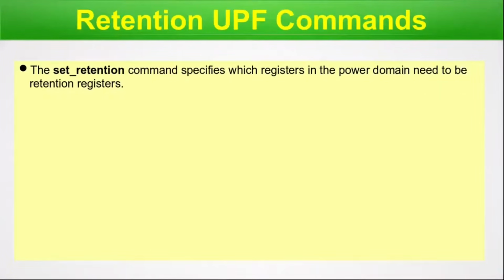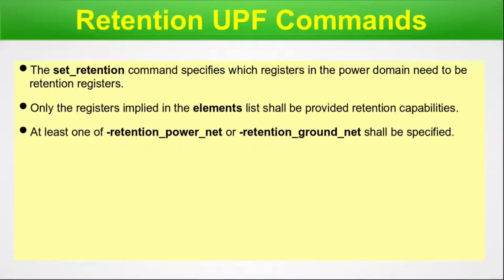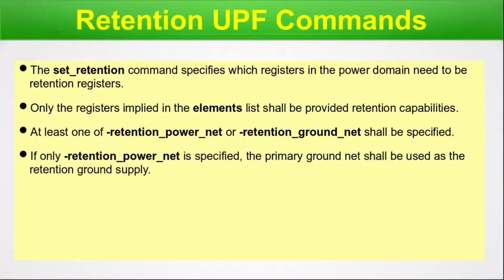The retention UPF commands. The set_retention command specifies which registers in the power domain need to be retention registers. Only the registers implied in the elements list shall be provided retention capabilities. At least one of the retention power net or retention ground net shall be specified.